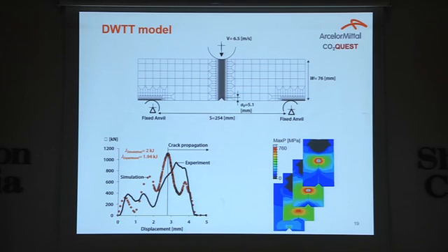As you can see here, in this test, it's much more difficult to simulate exactly the same wave transformation after impact. But we generally have good agreement if we integrate the area and measure the amount of energy. You see that we can almost predict the same amount of energy that we have in the experiments. A little bit higher energy is observed here, because we also have some dissipation of energy at our contact, which we do not take into account.